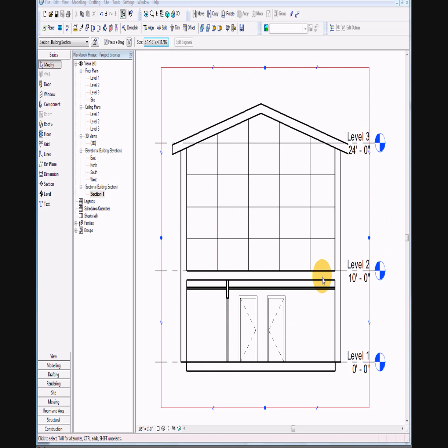So hit the control button. Let's go ahead and select the floors. And it wants to verify that they are generic 12-inch. And they are. Okay, now we need to remove some segments so we can put the door in. So go ahead and select part of the glass and hit add or remove segments. And then you should be able to remove that segment by clicking onto it. And then hold the control key down and we're going to select the perimeter here where we're going to put our door.